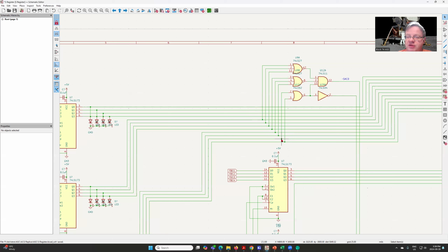So the low 10 bits are used to address the memory, and then we use the banks to switch in and out. By looking at the contents of our S11 and S12 bits, we can generate a control pulse to say whether we are accessing RAM or not. Because if we ever see information in these 2 bits, we must be accessing fixed memory, because that memory doesn't exist in erasable memory. We only use the low 10 bits for the erasable memory. And this basically gives us, as we talked about in the memory map, a signal to say, if these are set, we're using fixed memory.